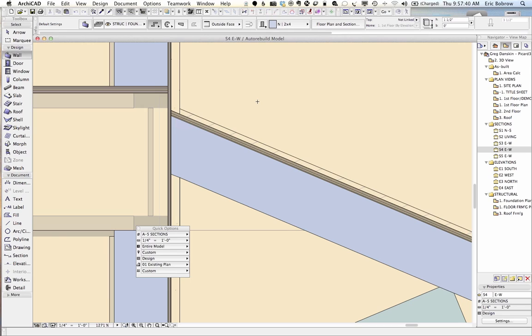The stucco itself above the asphalt shingles, I guess you would have higher priority on the shingles than the stucco, because the stucco will ultimately need to go up and have a screed and have flashing that would come down over the top of the shingles. All right, so the shingles should have higher priority.